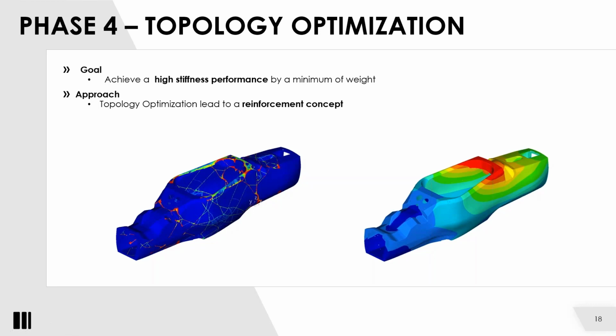Then, after you see where you have areas of high stress and load paths, we put UD stripes exactly along these lines and obtain an even higher stiffness of the monocoque, especially for the torsional load case.